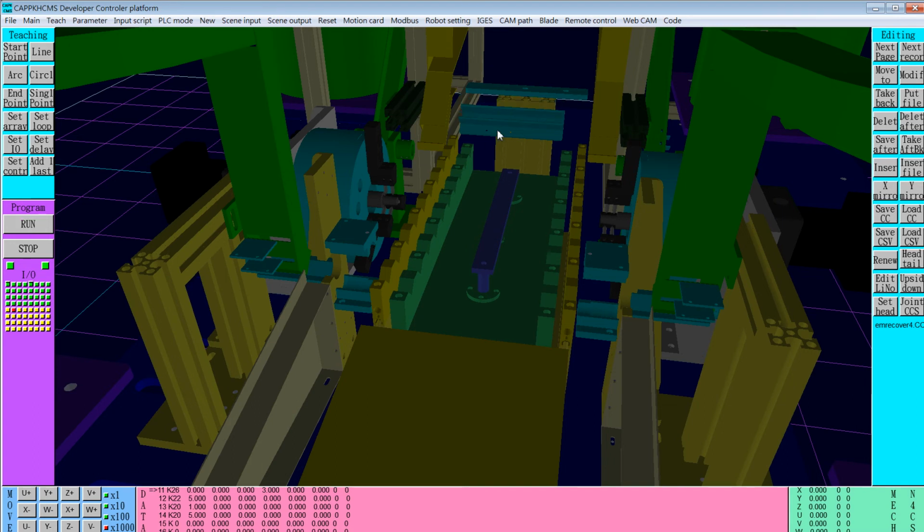Right. The lower thrust in first. This one returns back. Then the cutting plate thrusts in. The leaving plate retracts. And wait 5 seconds. The cutting plate retracts back again. Okay, let's see. 5 seconds. The cutting plate will return to home position.